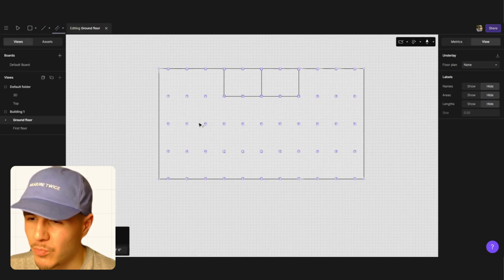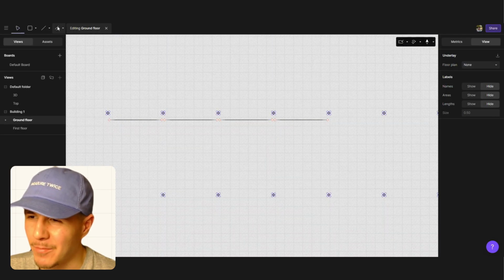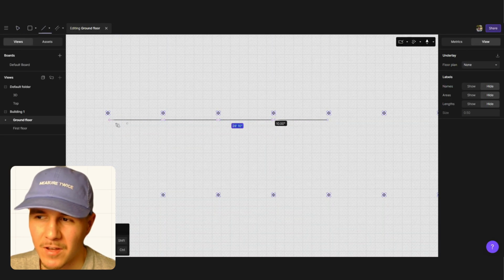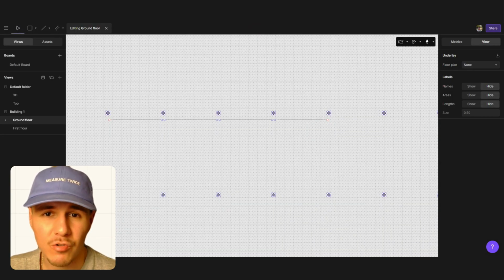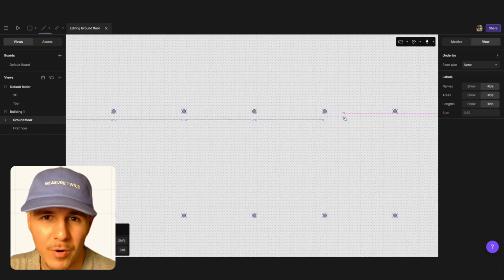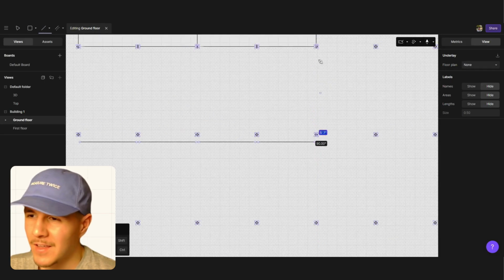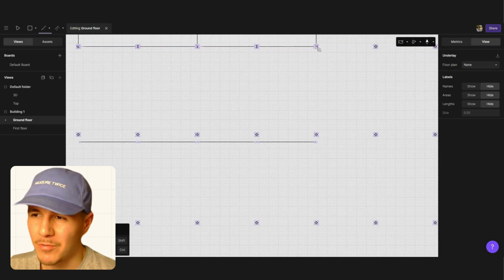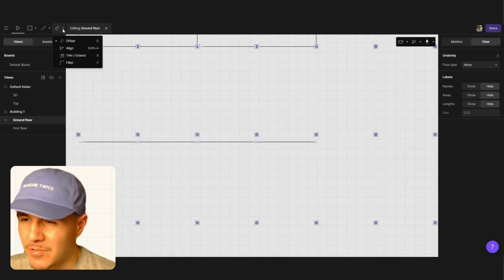So here are my first two rooms, and I find a better technique. Instead of looking for midpoints, I'm just going to use the offset tool again, because that's much faster. The way I'm calculating these dimensions is by the tiles that are showcased on the floor plan itself. I calculated that there is a certain number of tiles per span of the columns, and from that calculation, I'm able to pretty faithfully estimate the dimensions of the rooms, you know.